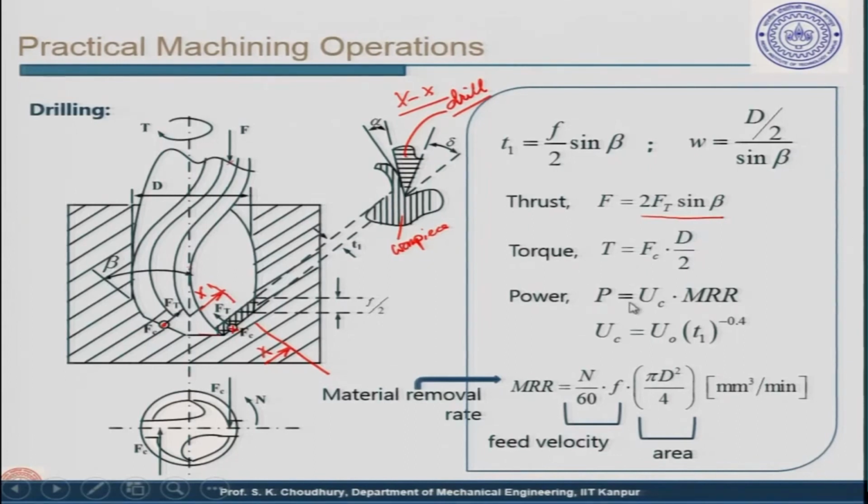Now, the power is given the same way as in the case of turning, shaping and planing. It is given by specific energy into material removal rate.